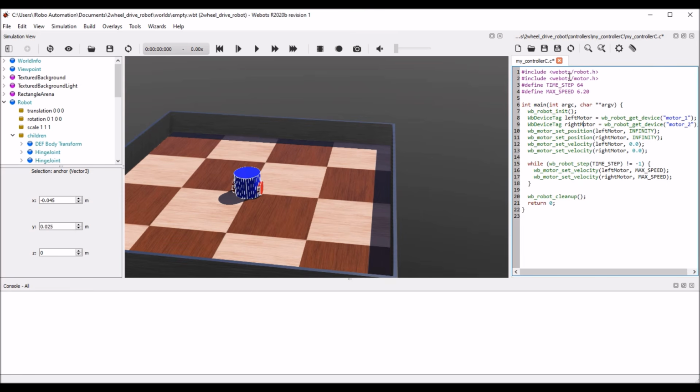First of all, I have created the controller and write your code. Okay, and after that you just click on the simulation, means start button, it will not work. First of all you need to save the program, and then you come to the robot. In robot there is a robot controller. In the robot controller, void is there, that means nothing is there.